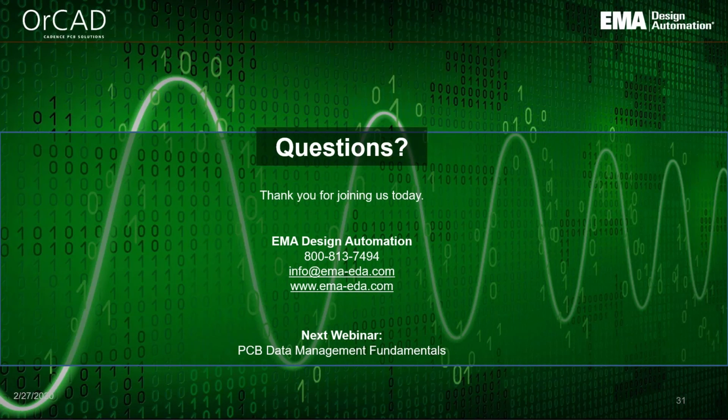So I have a question for Orlin here. What are the most important parameters for defining the stack-up material property and physical dimensions to achieve picosecond accuracy for timing and accurate impedance levels? What if the PCB fab house deviates from your modeled and simulated configuration?